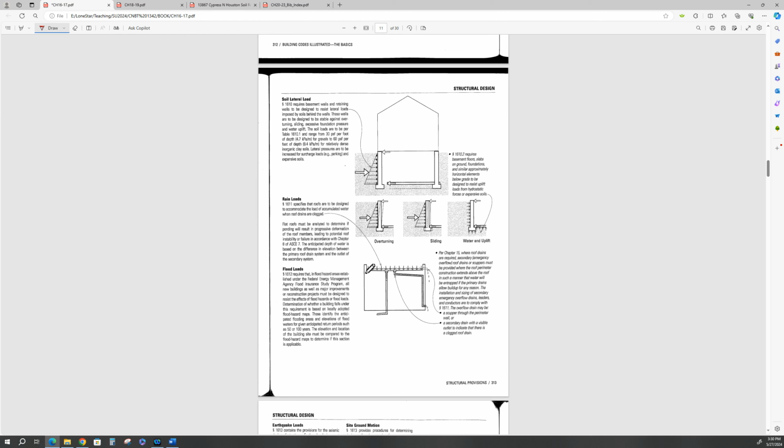All right. Flood loads. Well, there's not much you can do if it floods and water's moving fast. It's 62.4 pounds a cubic foot at whatever speed the water's hitting the structure at. It'll move concrete barriers across highways and everything else. Now, rain loads on the roof. We talked about this in a previous video.